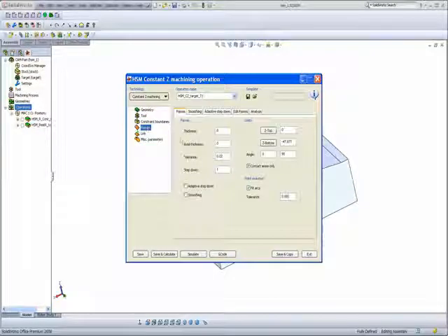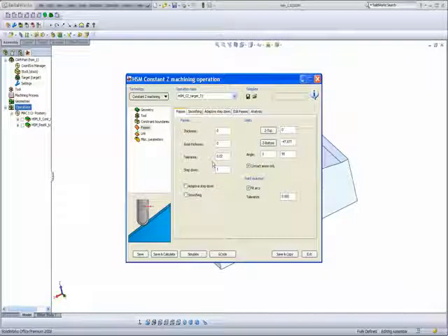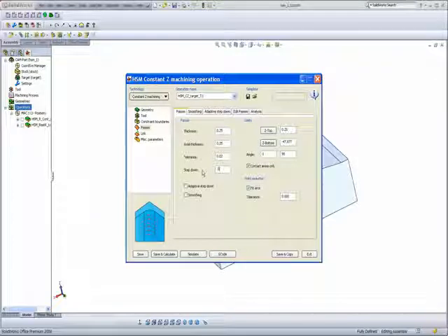In our passes area, we'll be leaving a thickness of 0.25 millimeters, and our step down will be every half a millimeter. Now, since we'll be working on constant Z, and constant Z works best on steeper walls, we'll limit our area of work to work only on walls, as you can see in this picture, between 40 and 90 degrees.